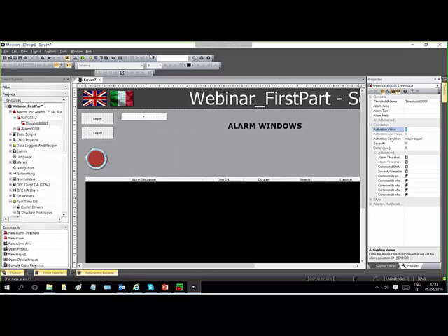Have you seen here the speaker read the message because I enabled this feature? About the description, you could add the description as I did here in the threshold directly, and Movicon will show the description. You could work with the threshold name. You could also dynamically write here in the alarm text another variable, F1 will explain. You can embed a dynamic text over the description from another variable. It could be a string, it could be a value.